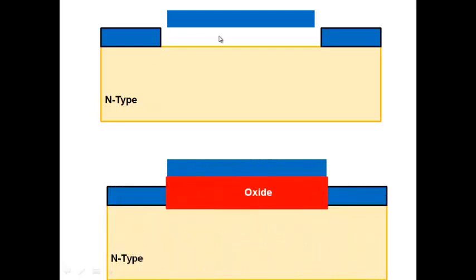You realize that air only acts as an insulator. A very good insulator in a silicon system is silicon dioxide. So what you do is you deposit silicon dioxide and you put the metal on top. Here air was serving as an insulator; here oxide serves as an insulator. And then you end up with a metal here, oxide here, and a semiconductor: metal oxide semiconductor. We know that this device exhibits transconductance and is a transistor based on the field effect principle, where you modulate the conductivity here by applying a voltage here. So that's how this particular device gets the name metal oxide field effect transistor.